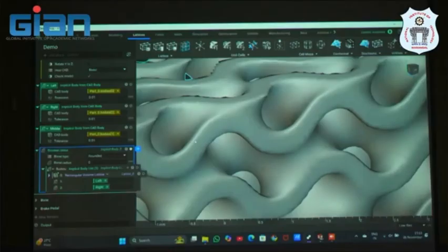In 3D models also, for complex structures during analysis, in industries they will prefer the tetrahedron instead of the hexagon to get the correct capture. But the problem with the tetrahedron is that it will increase the element sizes. That's why the STL file size will be very high. Tessellations will increase, and if the element size increases, obviously the simulation time will also increase.